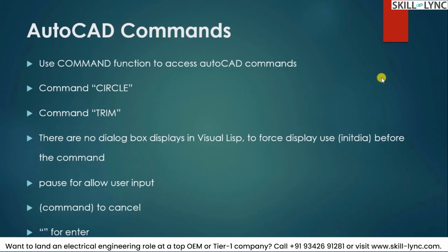So finally, the double quotes open and close without any space translate that AutoLISP has to give the enter command. Enter as in our keyboard enter command, the new line command that we are doing, right? So that is translated using the double quotes open and close that AutoLISP interprets. So this is the usage of AutoCAD commands within your AutoLISP environment.